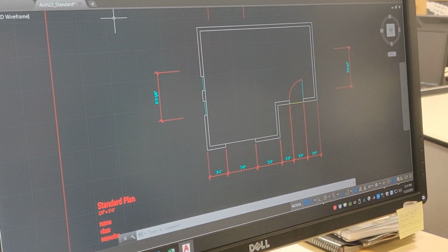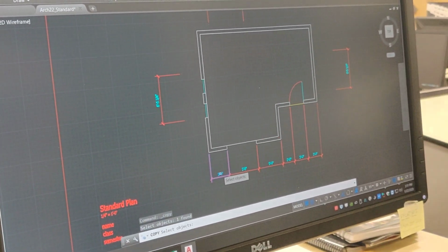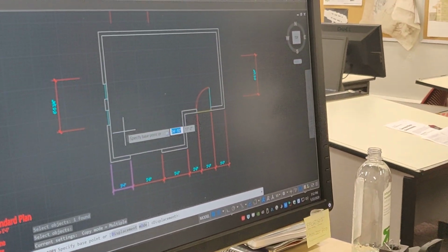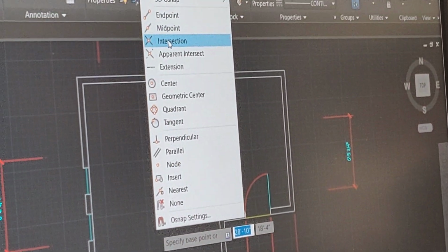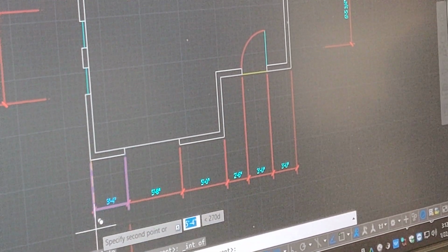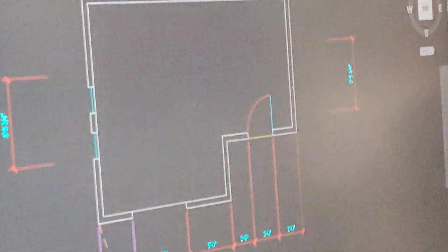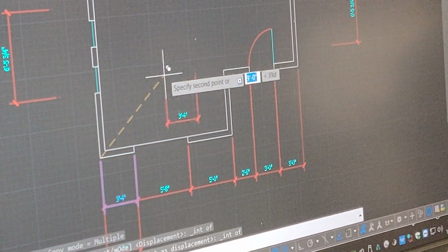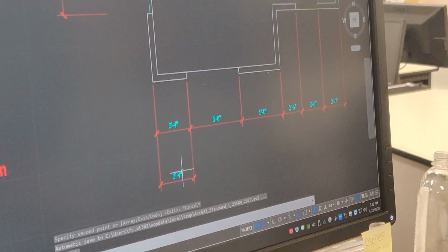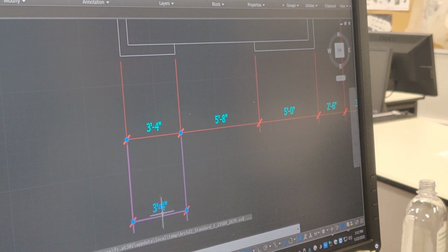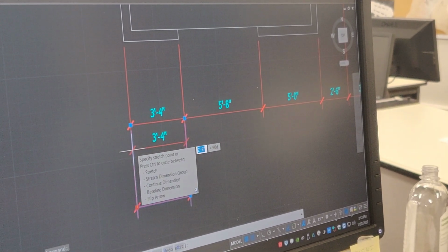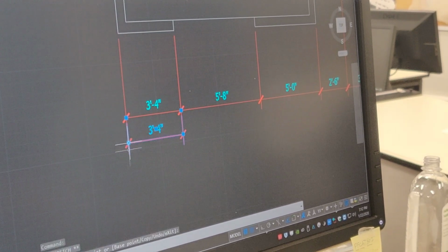So all I'm going to do is copy this guy again, but now I'm going to move, copy it from this intersection. So shift right in from that intersection right there to right there, okay? And I'm just going to kind of eyeball this guy, and I'm going to move this up a little bit so it's a little closer. Right about there looks pretty good, okay?